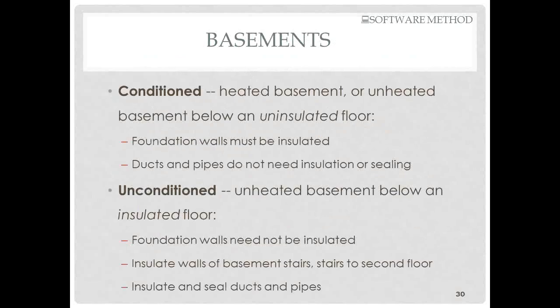This is how the code defines basements in terms of conditioned or unconditioned. A conditioned basement is obviously a heated basement, but the other way a basement could be considered conditioned is if it's an unheated basement below an uninsulated floor, which is the way we build most houses in Vermont. In that case, the thermal envelope is the foundation wall. You'll end up insulating the foundation walls, but you do not need to insulate the basement ceiling. And any ducts or pipes that are in that basement do not need insulation on them because they are considered to be within the conditioned space.